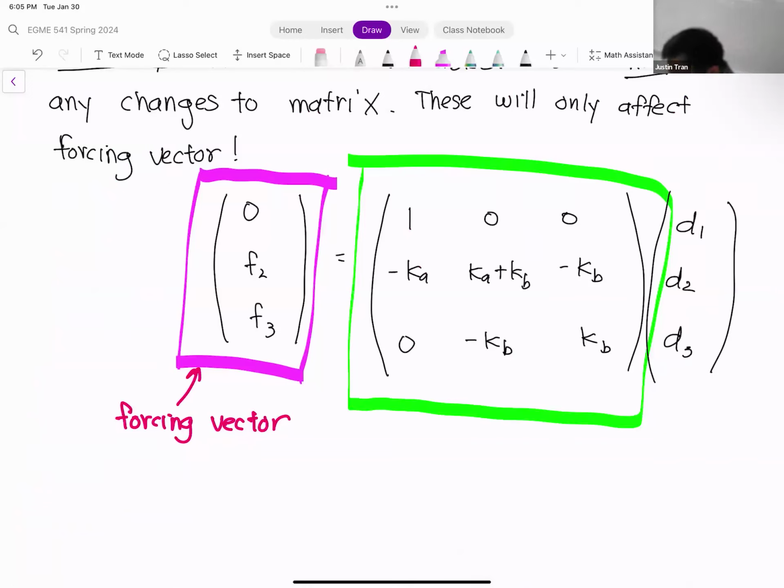And so if we know that our Neumann boundary condition is being applied on node 3, that tells us that the nodal force on node 3... Yes, so here you still have the first row replaced with the Dirichlet equation. Do we keep it that way? Yes, we do.